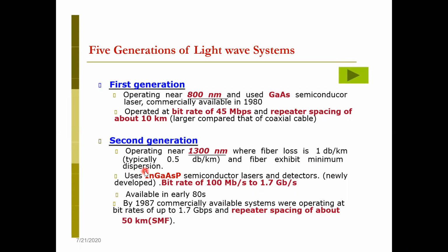Dispersion is again a second type of loss. One type of loss is where the amplitude decreases, the signal strength decreases. So this is what we are talking about. Fiber loss, 1 dB, we are talking usually about the signal strength. That is the attenuation loss. Now, another kind of loss, and that is actually a challenge still, is the dispersion loss.